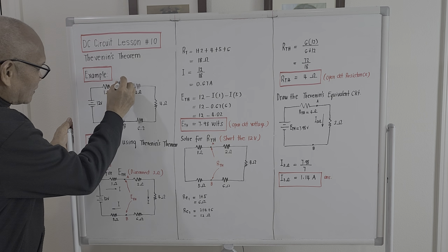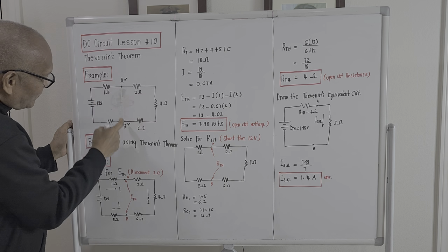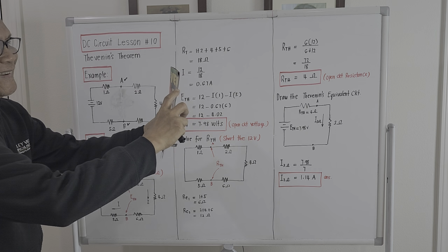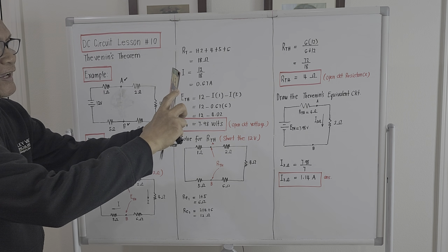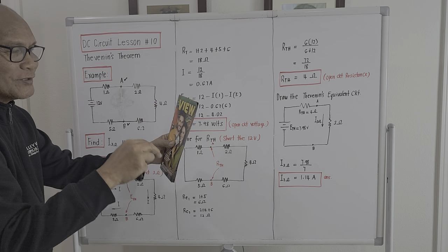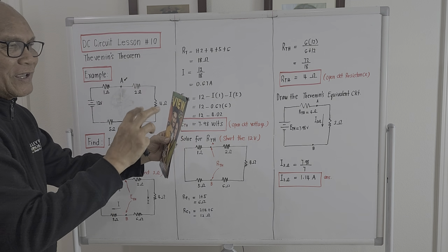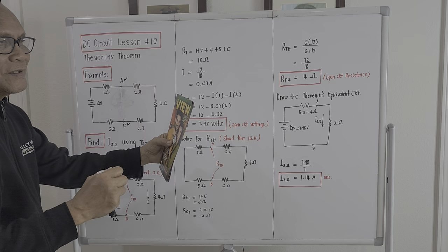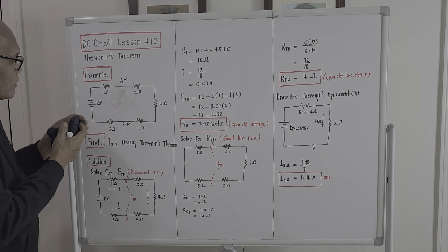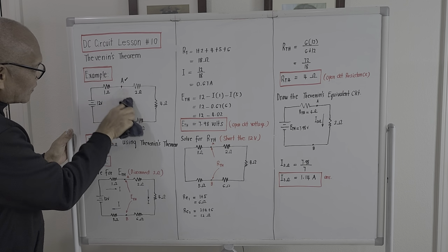So there is a terminal A here and terminal B. So it seems this terminal A and B is actually the one emanating from the active network, right? And what will be the configuration of the circuit inside? Whatever the configuration that was given in the problem, that's the configuration inside. There's a voltage source and there are resistances inside. So if we try to disconnect, hold on, I will erase this one so it will look neat.